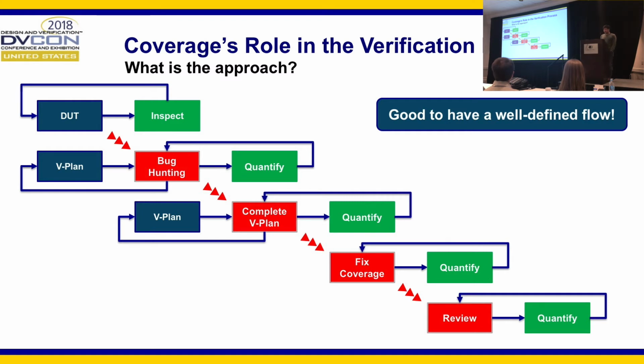Once you complete your verification plan, you can still have big coverage holes in your design. You analyze the coverage holes: what is the reason why you have them? On top of that, you write assertions to cover them, and you run Quantify to see if you covered the holes.